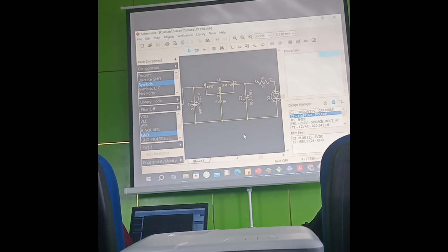I'm going to repeat that again. But the labeling: after finishing the entire circuit diagram, then you start labeling all the parts, like the live, the neutral, the nets. As we are doing it, we are labeling. When you now want to attach it to the PCB, just update, because my own is complaining that I didn't complete the labeling.